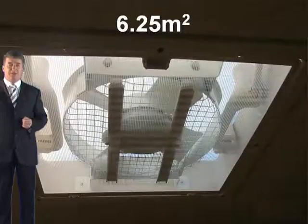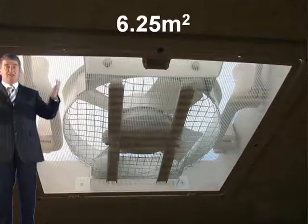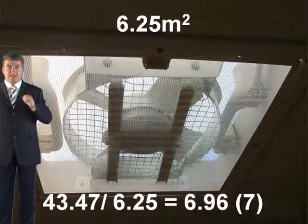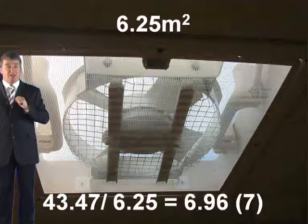So now we need to consider how big ventilators are. Well, ventilators themselves don't come any bigger than 6.25 square metres, and that's because they can't test them. That's the biggest they can get in the test rig. So you're not going to get ventilators bigger than 6.25. Now, if you divide it out, 43.47 by 6.25, you know at the very least you need 6.96 or 7 ventilators. So you're going to have at least 7 in that area. That's the minimum. Now, where do we locate these ventilators? Let's look at where we locate them now.